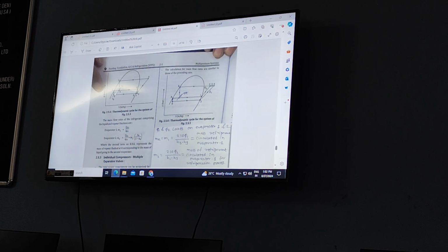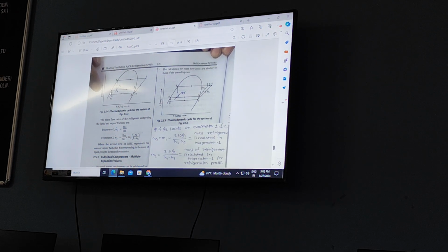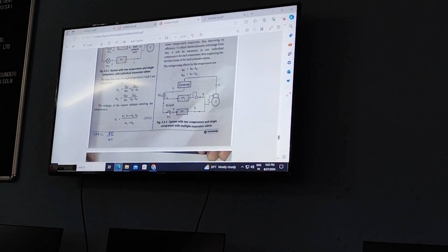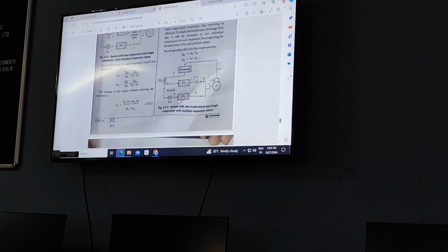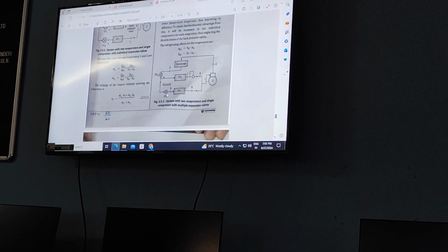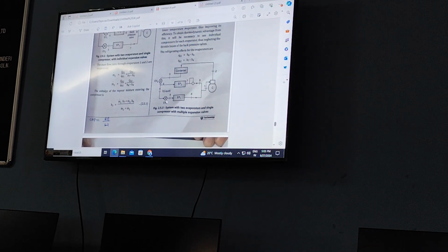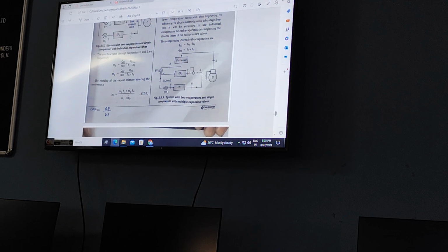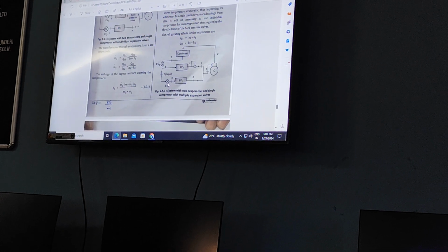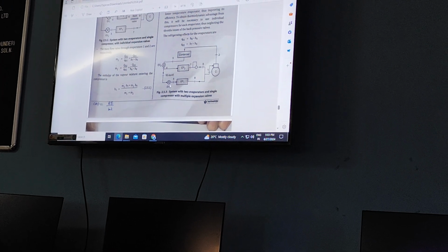That is equal to mass supplied from this expansion valve plus during this expansion valve. Which expansion valve? This. During this expansion valve of evaporator 1. What is the input of expansion? Liquid. After expansion, pressure reduces and some of the refrigerant evaporates and it carries latent heat. That's why the remaining refrigerant temperature is reducing. Evaporative cooling, right? Same principle that is used in the earthen pot.